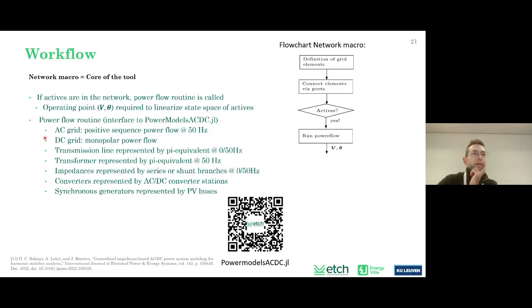And then we have power flow representations for the different components: transmission lines, transformers, impedances, converters. Converters are modeled by an AC/DC converter station, and synchronous generators are represented as a PV bus. So nothing fancy, all the things you know from a basic course on power system modeling.